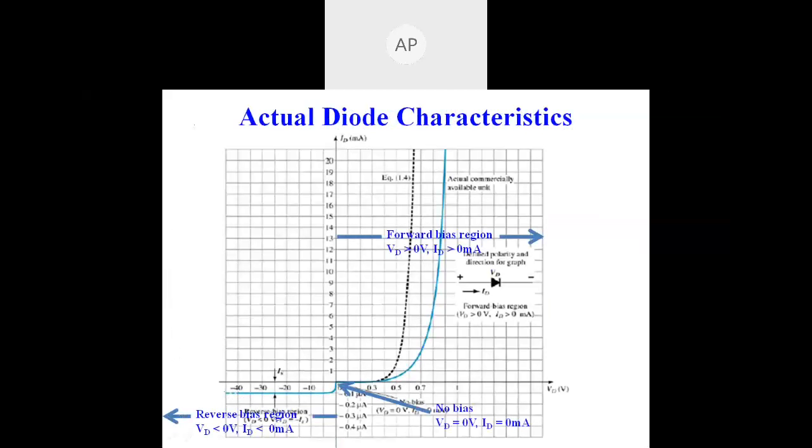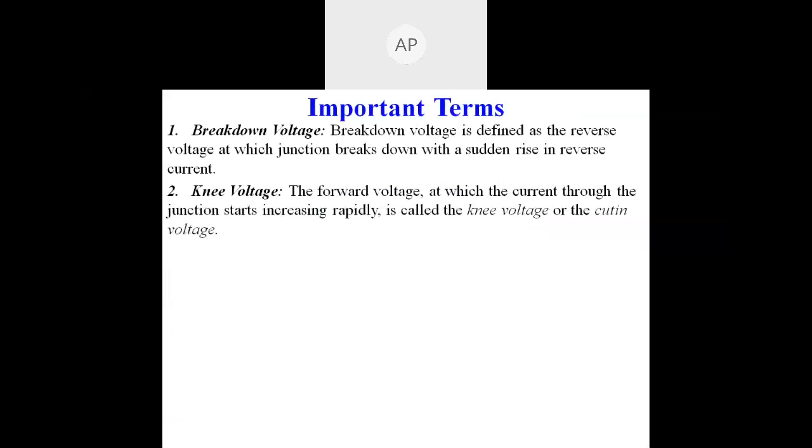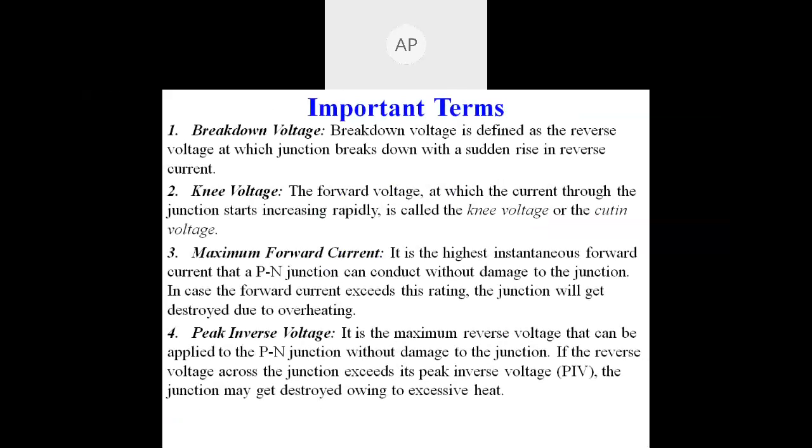Observe that it is a dotted line. If you go beyond that, the barrier potential will break, and the movement of carriers, electrons and holes, goes on. Current will start, but as the barrier potential breaks, more current flows, and this larger current will make the junction heat up more.